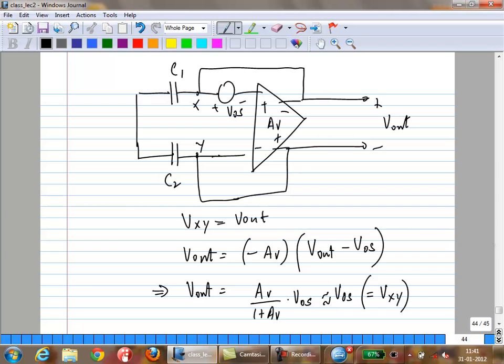So, what is going to happen? Vxy is right now V offset, right? So that offset voltage is stored across these capacitors as a DC voltage. Okay, so that in the next case, you're going to open this, apply the input here. So the actual input you're going to get is going to be the V in signal plus VOS, and then you're going to get a minus VOS, so that you apply V in directly across this amplifier. Okay, that is the idea. You store this VOS across the capacitor, you are basically storing it and adding it to the input, and then it gets subtracted from this, and only the input voltage gets applied at the input of this ideal amplifier. Okay.